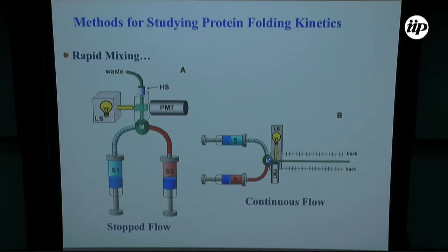Because you can imagine, this is a normal channel like this, and you keep pushing sample over here to make your measurement, in a few minutes you will waste, like 100 milligrams of protein that it took you like 3 months to make, right? So when you actually are able to micro scale these mixers, and I'm talking about channels that are typically 10 microns in depth and maybe 100 microns in width, so they are much smaller than this, then your sample is not wasted so quickly, and also you can get a faster mixing.